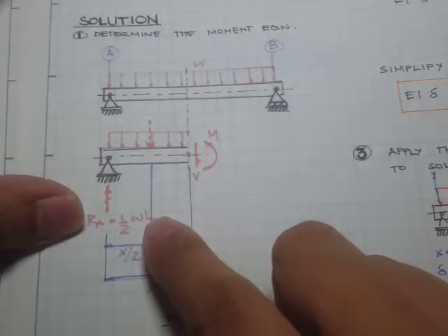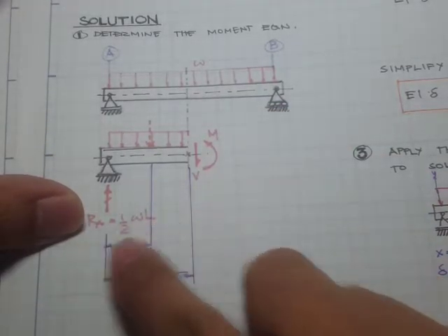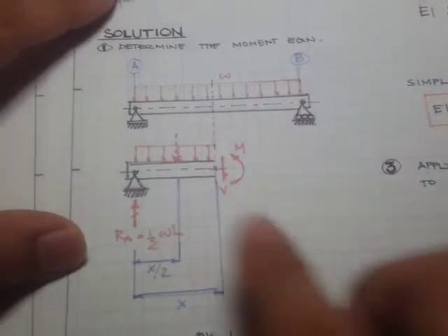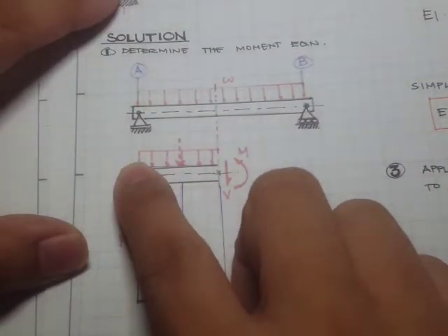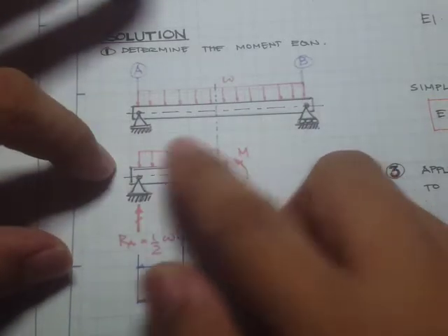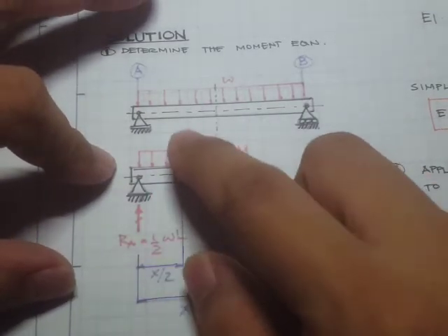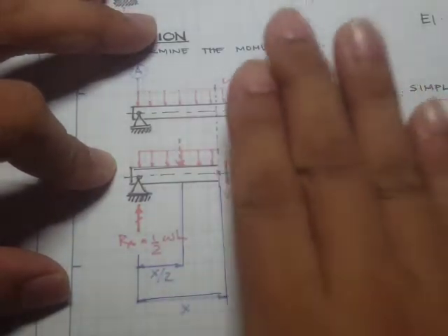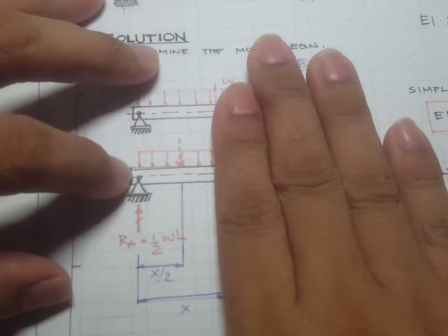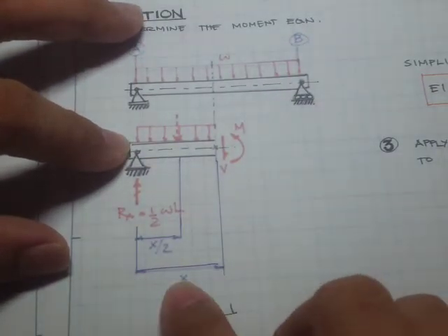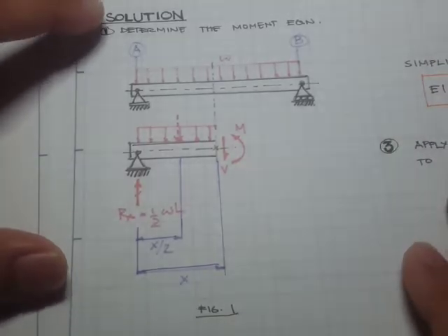So we have to multiply that by the length so that we can obtain the unit of a load. And since this is a distributed loading, we can also express that in terms of its resultant, and the resultant force actually acts at the distance x over 2. Okay, so from the section cut to this point A, we denote the distance x because it's an arbitrary distance.